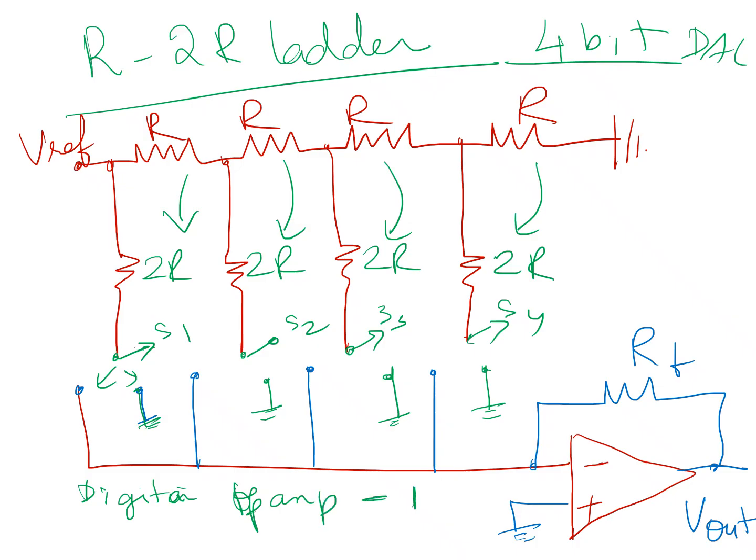If the switches S1, S2, S3, S4 connected to the 2R resistors are connected to the ground, then the digital input is 0. So by modifying the binary weighted resistor, a proper configuration of the R to 2R ladder network provides high resolution, and unequal values of resistors leading to bulky resistors are avoided in this kind of R to 2R ladder network.